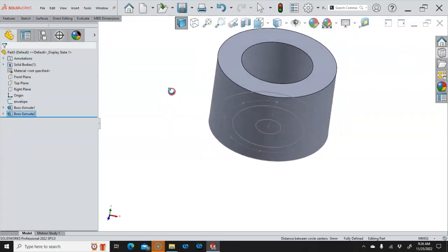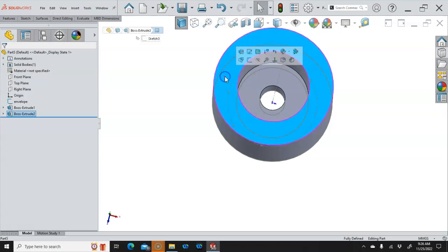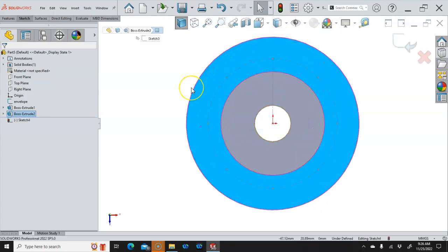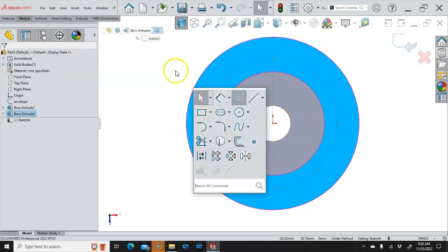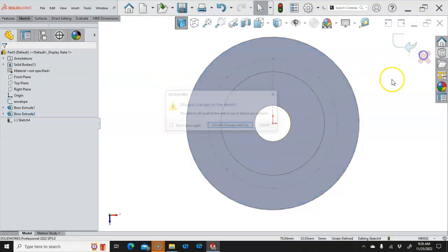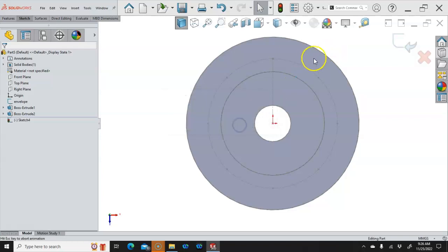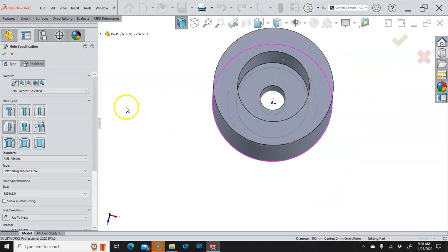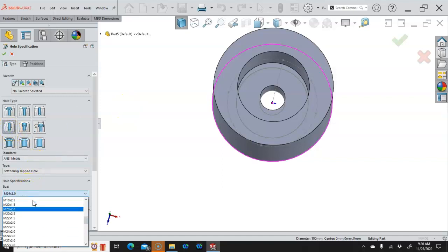All right, the hole's already in there. So we're ready for the hole wizard item. And oh, I clicked on the wrong one. So S key, hole wizard. There we go. We still are in the M24, so we'll come back to the M8 by 1.25.